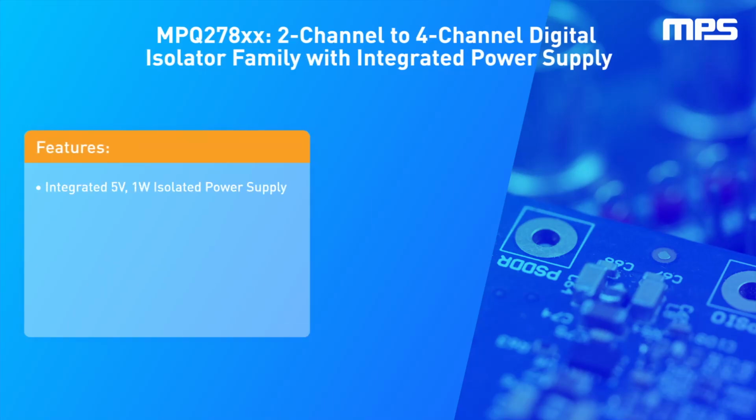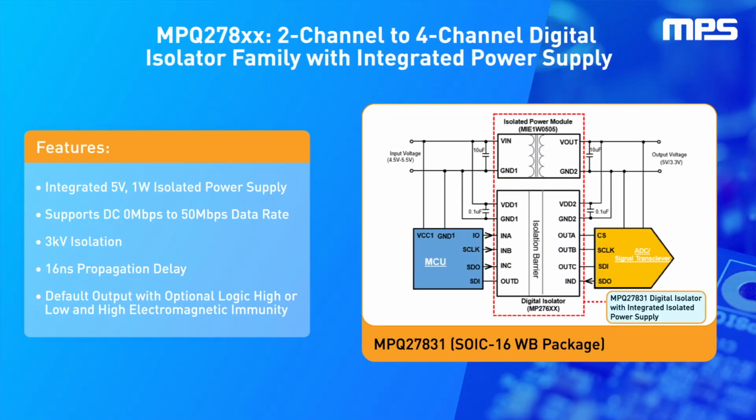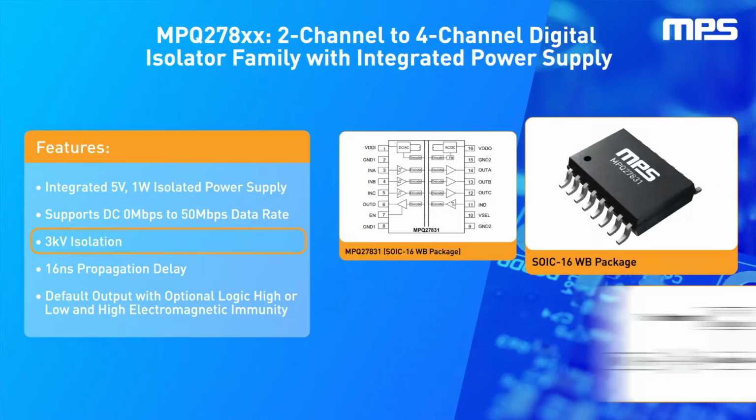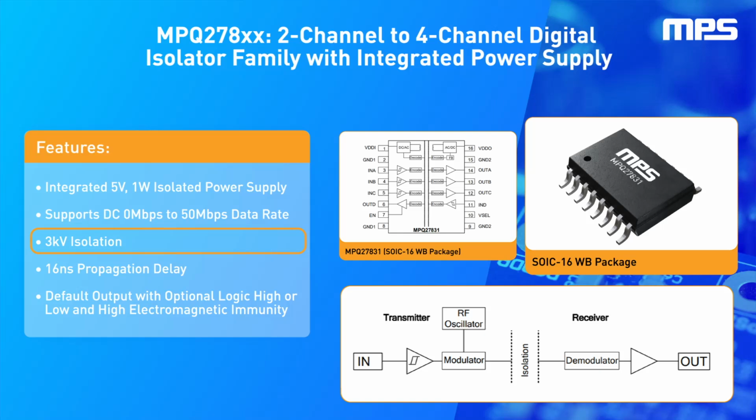The MPQ278xx family of digital isolators with integrated power uses capacitive isolation technology to support an isolation voltage rating up to 3 kV. This isolator provides small size, low power consumption, and higher reliability operation compared to traditional optocoupler isolators. The MPQ278xx family also integrates one isolated DC to DC converter with up to 200 mA of output current and 3 kV of isolation, providing isolated power for the isolated data port.